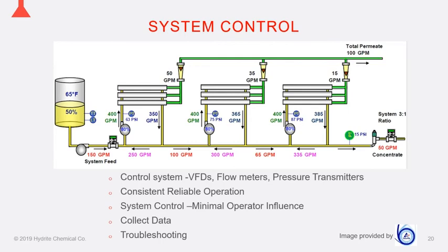Now we're feeding loop 3 65 gallons a minute. That's the remainder. And at this point, we now have increased our solids even more. We're probably about 11.5% solids feeding into loop 3. And again, we need the 400 gallons a minute flow because we've got the 3 vessels that need at least 100 gallons a minute.